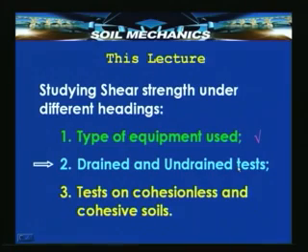Now, it is very well known, we have discussed it sufficiently often, in both my lectures on consolidation as well as in this, that when a soil is saturated and when a load is applied, be it compressive or be it shear, if the drainage is permitted, then the load gets transferred to the soil grains as intergranular stresses. Otherwise, they remain as neutral stresses in the soil in the form of excess pore pressures until the water drains off and the stresses are transmitted to the grains.